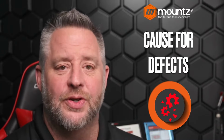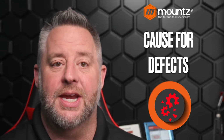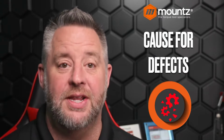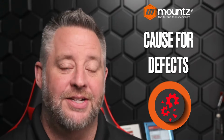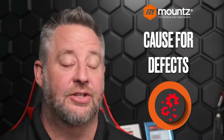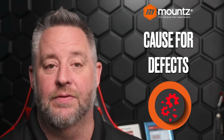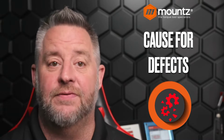So causes for defects that we look at typically, the biggest contributor to defects is going to be the operator themselves. Sometimes the operators aren't paying attention to what they're doing. They can over tighten things, under tighten things. They can skip fasteners, or they may let go of the trigger too soon in a fastening operation and leave fasteners lifted.